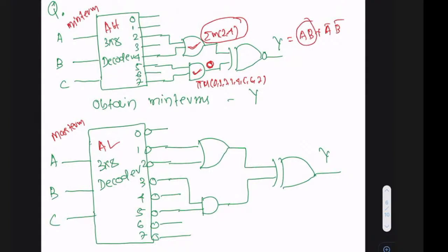If you say min term 0, the meaning is different. It means that if you apply the input 0, 0, 0, the output is 1, which is not correct. That is what you do not want to say here, right?